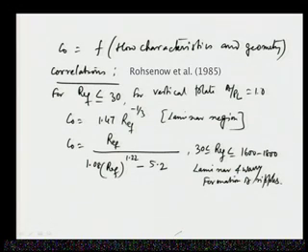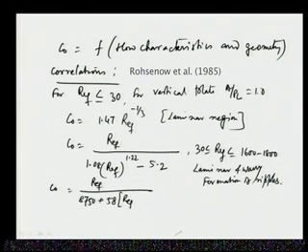And then another one is the condensation number is Re_f by 8750 plus 58 Re_f to the power 0.75 minus 253, into Pr_L, the Prandtl number of the liquid, to the power minus 0.5.